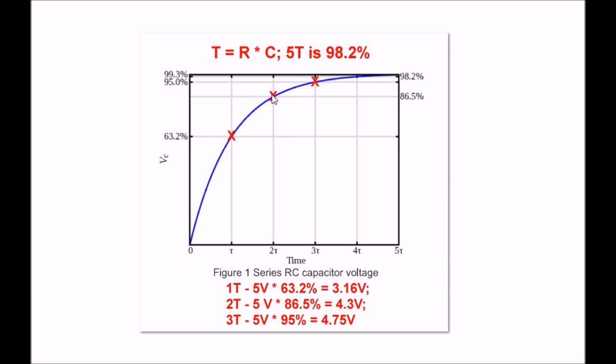There might be a couple of tenths of a volt difference in the way they fire. Of course, by 3 time periods, I'm up to 3.75 volts. So this is beginning to suggest a solution. If you're going to do this kind of switching with parallel MOSFETs, you need to go to a higher voltage. But even 5 volts on stuff that fires between 3 and 4.3 volts is still an iffy proposition.